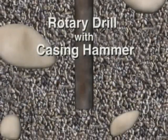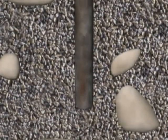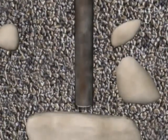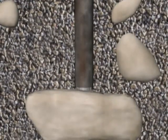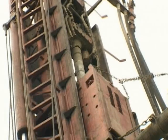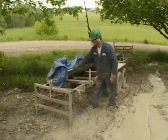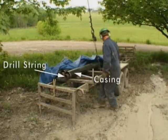The drill-through casing driver system is unique in its ability to both advance the hole and casing in one operation. The rig contains a casing driver head located below the rotary head, enabling the advancement of casing to directly follow the drilling of the borehole. New sections of casing are prepared with the drill string sections inside and are hoisted and mounted into position together.